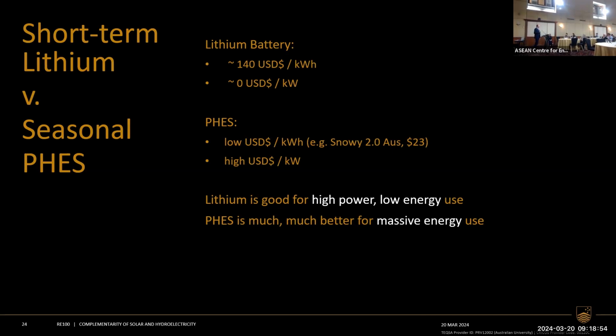Lithium is good for high power, low energy applications, for frequency control, for voltage control, for short-term usage. Pumped hydro is much more useful for huge energy storage, for multi-day, intraday storage.